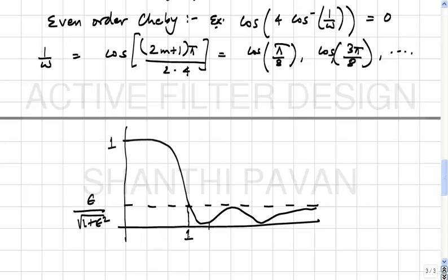Everything, it turns out, is a special case of a transmission line, right? An inductor can be thought of as a transmission line with a very high characteristic impedance and a very small length, and a capacitor can be thought of as a special case of a transmission line with a very low characteristic impedance and again a very short length.